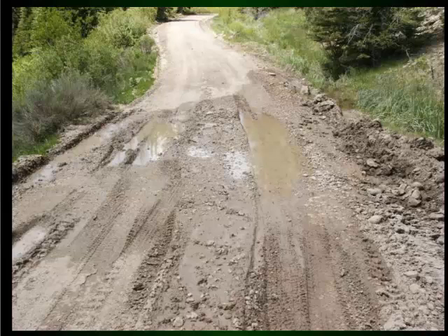And this filter cloth will keep that from happening. It is kind of expensive, but if you're rocking a road, rock's expensive. And on my own property in Oregon, I had a place where I had to put down about 200 feet of it going across the clay section. But there was just no way. It just swallowed rock. Basically, the rock just disappears.